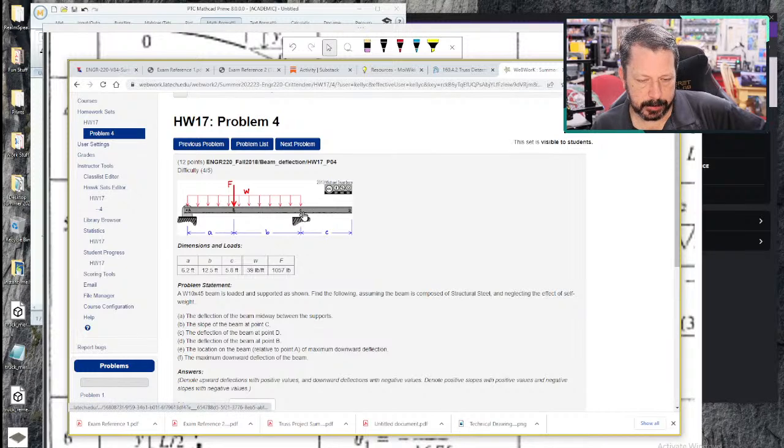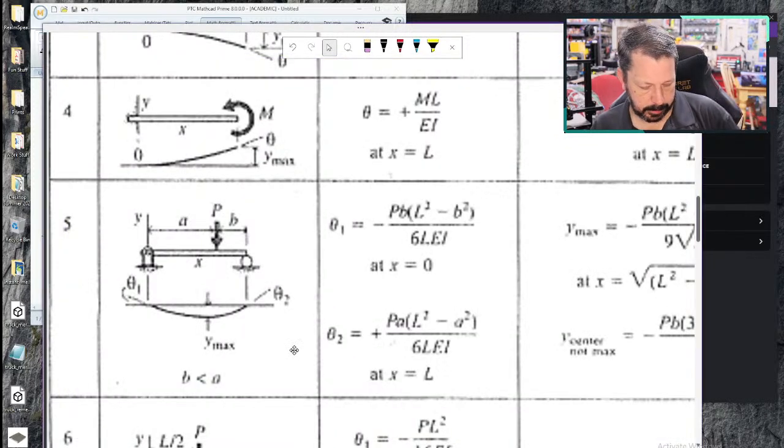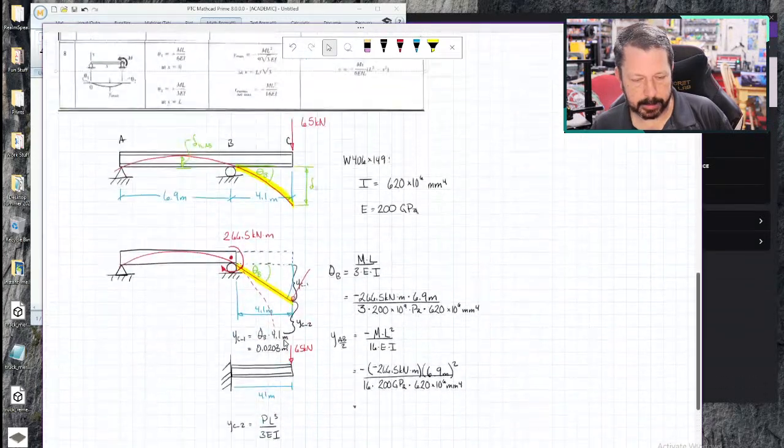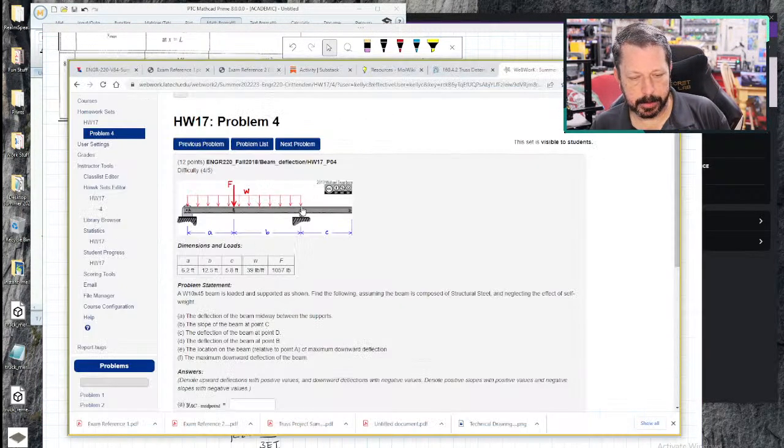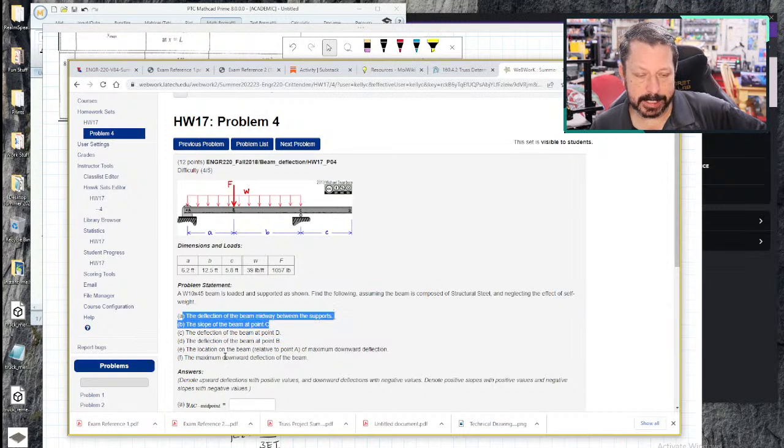The interesting part with this one is similar to what we did just a minute ago by calculating the deflection here, where you find the slope at the end of C. Both this point load and this distributed load create a slope here, which don't bend section CD, they just send it upwards, and you just use the angle at C to figure out how much it bends upward, because one of the things you want is the deflection at D. This problem, if you picked one of these, just one, not all 6 of them, would be on the scale of the hardest thing you would do on an exam 3.